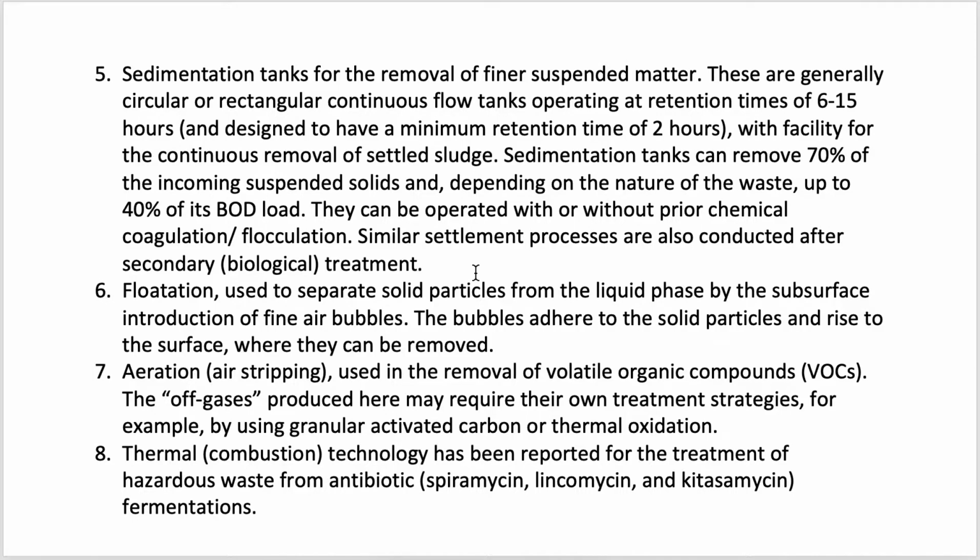During this time, the fine suspended matters settle down at the bottom, so they can be removed. From time to time these sedimented portions are removed. This sedimentation of finer suspended matters can be achieved by using tanks.